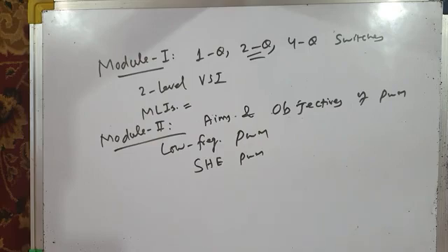We have discussed this low frequency PWM, selective harmonic elimination PWM technique in quite detail using the switching angle plane. We have tried to eliminate the fifth harmonic component of inverter output voltage, the seventh harmonic component, both components, and combinations of those. And we have discussed offline optimized PWM techniques and stored waveform PWM techniques using low frequency PWM. That was about module 2.